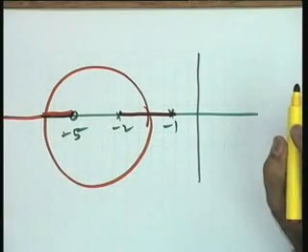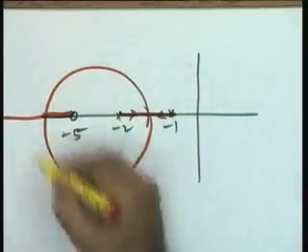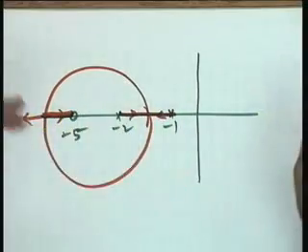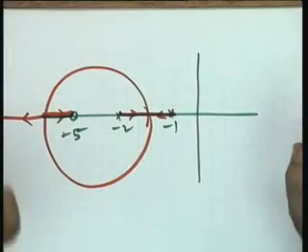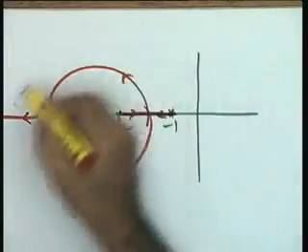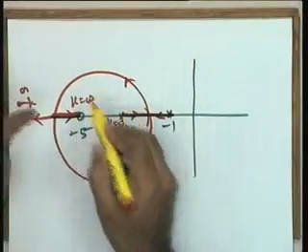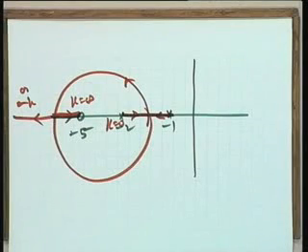That is also important. Therefore all the points on these red lines are the root locus branches for some value of k. As I will show you, k can be scanned this way: k equal to 0 is here, and k equal to infinity is at this zero branch.